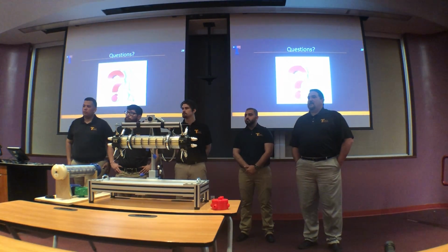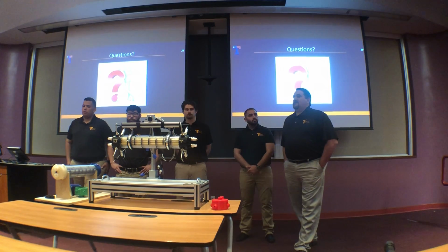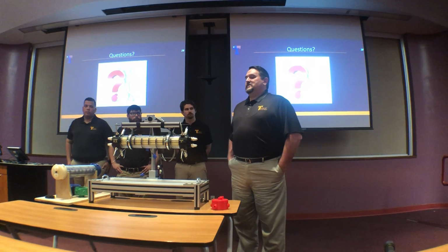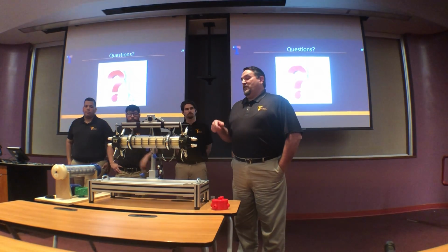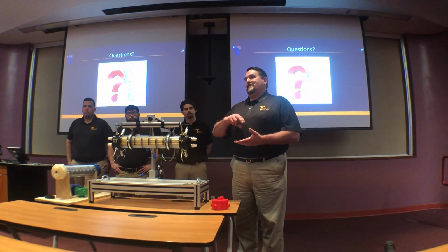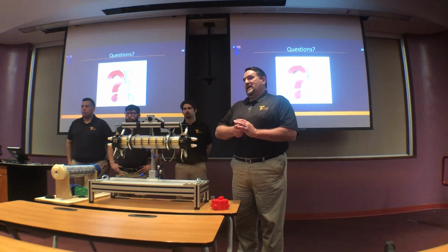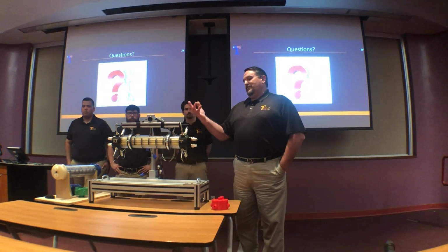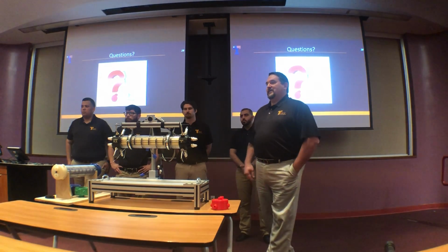How did you thread your ABS? We initially tapped the ABS, and on a couple of our prototypes, because of the NPT, the way it's built, when we would thread it in there, it would be prone to cracking or layer separation because of the way 3D printing is just layer on layer on layer. So on these, we actually printed the right size hole, heated up the brass fittings, and then did a heat set, where I put it down into the plastic while it was hot and then let it cool. And it seems to be working pretty well, to where then you have a reliable brass fitting. You can put in and out whatever kind of fittings you want to.